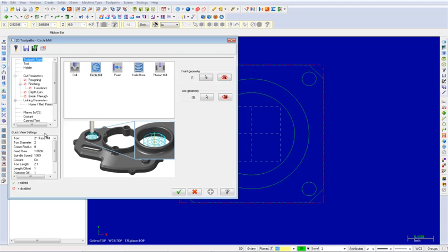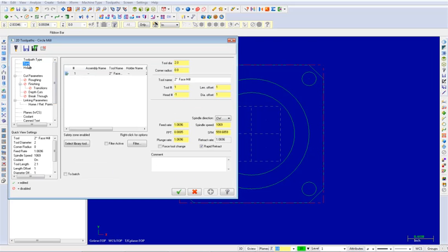In the Toolpath Type page, you will notice that the Circle Mill icon has been selected. We will now choose the 1/2 inch flat end mill from the library and set the tool parameters. To do this, select Tool from the Tree View list. From here, select the Library Tool button and then disable Filter Active.